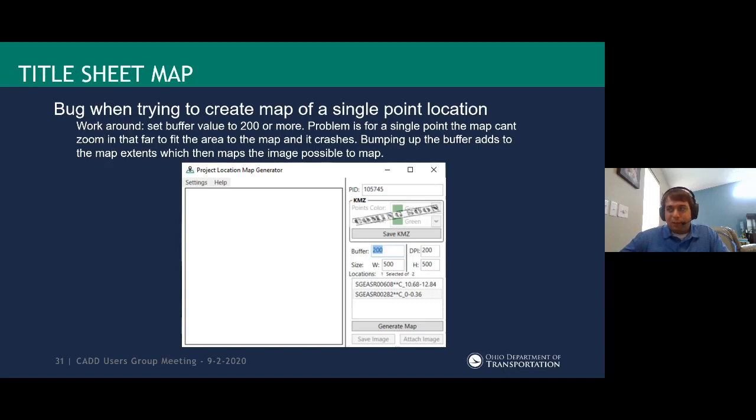you can still use them. They're not in this standard. You can go to the OhioDOT CADD standard and get them. They're in the county maps folder. They're just a DGN per county. As a stopgap, just note that they haven't been updated in a decade. But if you need to use them, you can go grab them and get your work going.